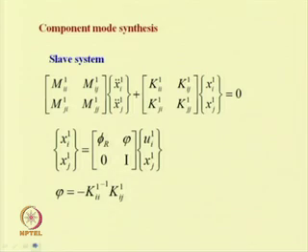Another method that we can use. In the previous two equations, when we are using this modal reduction method, the nonlinear terms' forcing vector rotates between the physical coordinates and the modal coordinates. To avoid that, one can use the component mode synthesis method.